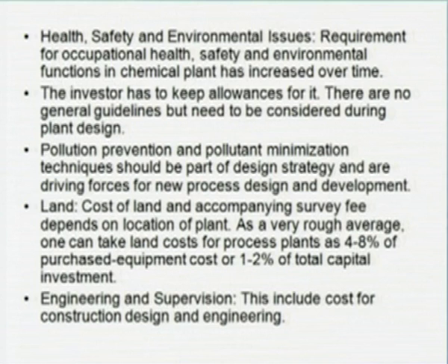Then land. The cost of land and accompanying survey fee depends on the location of the plant. Site survey and site related aspects we have seen in greater detail in a previous lecture. As a very rough average, one can take the land cost for a process plant as 4 to 8% of purchase equipment cost, or 1 to 2% of fixed capital investment.